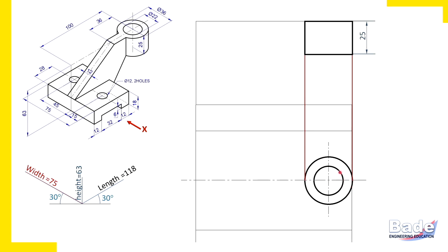And the hole, project its horizontal dimension, and it is a through hole from top to bottom of the cylinder. Draw dotted lines. So where is this hole in the front view? So this rectangle. Remember, the hole has a circular edge at the top, and this edge appears horizontal and it coincides with the edge of the cylinder. So this rectangle is a dotted rectangle, and that is the hole in the front view. Now when a cylinder appears a rectangle in a view, then you should draw its axis. So we have drawn the axis of the cylinder or axis of the cylindrical hole.